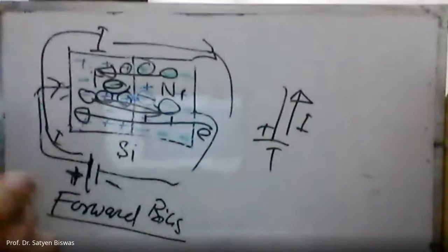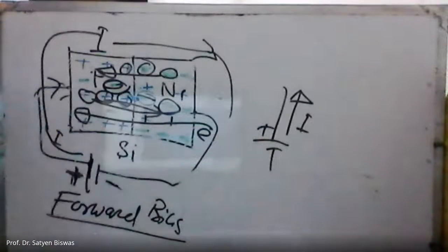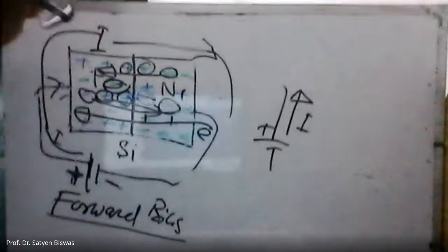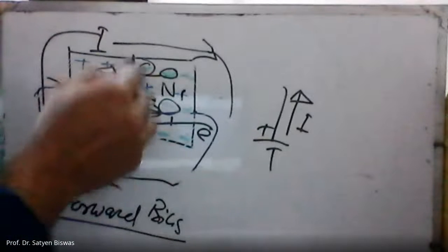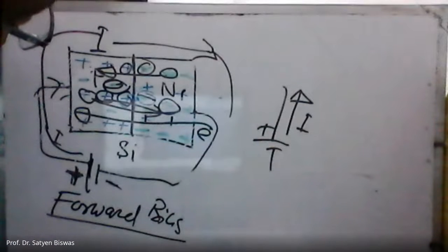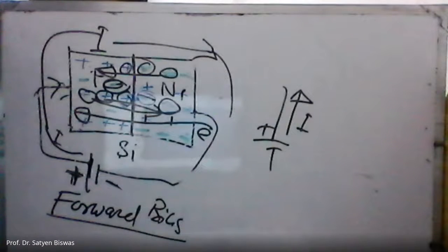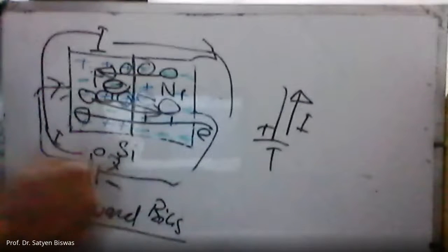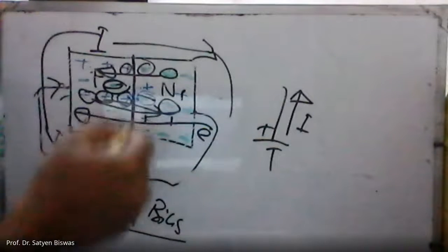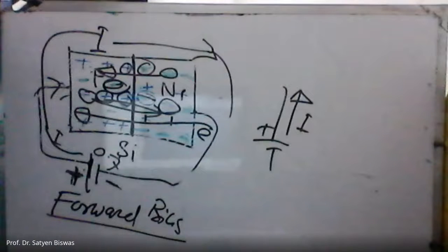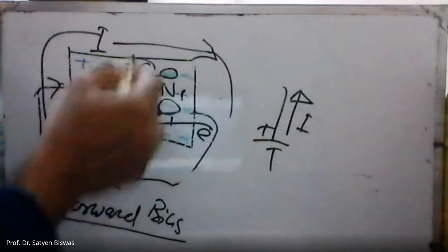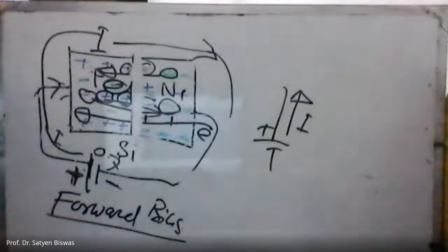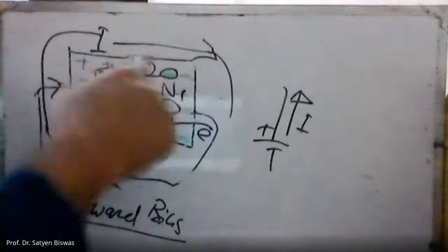And what happens to this boundary line? I put a line here. When you apply positive voltage, up to 0.7 volts or a little more, what will happen to it? The virtual line will disappear. When you have forward bias, there will be nothing. So no boundary line.